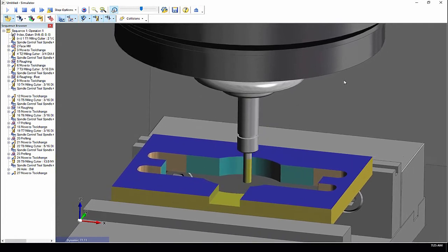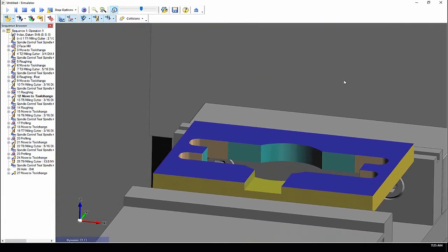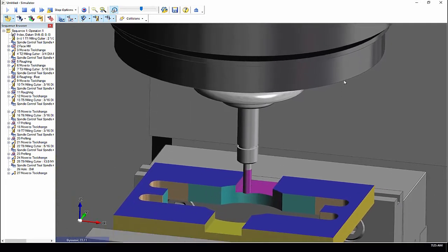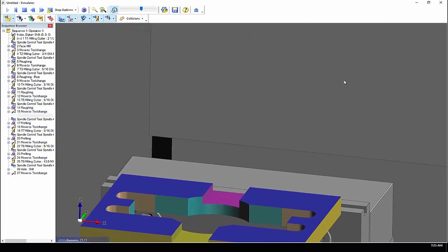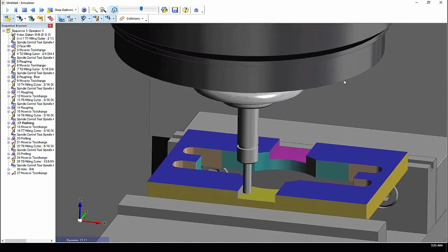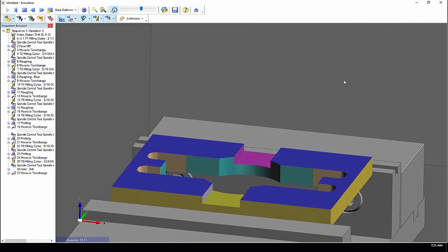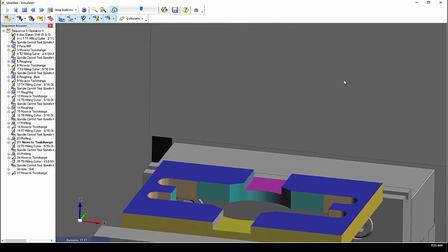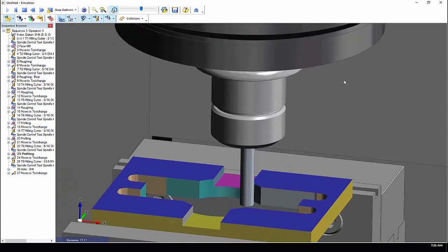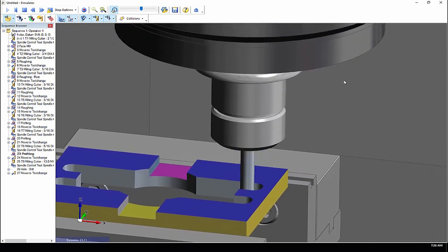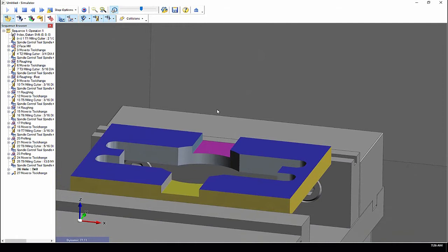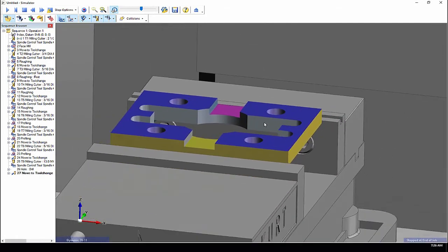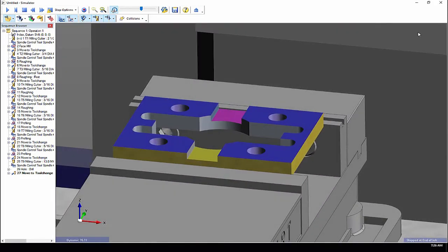Adding the vise, the machine can also have a user interface if needed. Next, the tools were selected by decisions based on the machinable features of the part. The tools were applied in a preset order defined by the process. Some customers have multiple processes and can apply them to the part dynamically. The speeds, feeds, and depth of cut or other details are driven by your proven process. A video simulation can be output with the setup sheets as well as process drawings to aid the operator in setup and production.